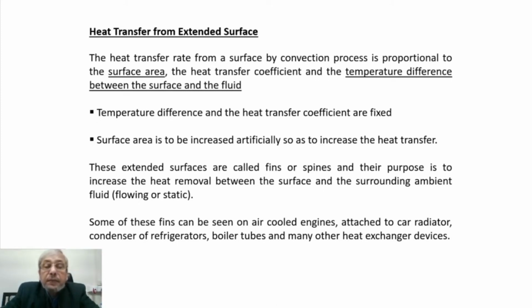So these extended surfaces are called fins or spines, and their purpose is to increase the heat removal between the surface and the surrounding ambient fluid. The surrounding ambient fluid may be a flowing fluid, or a static fluid. Some of these fins can be seen on air-cooled engines, attached to car radiators, condensers, refrigerators, boiler tubes, or many other heat exchanger devices.